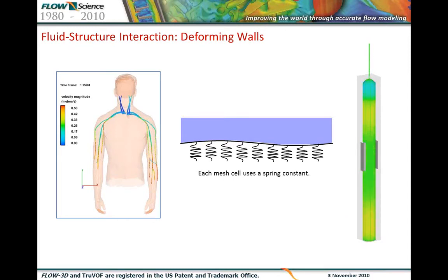As far as the physical details here, the computational cell has a spring constant normal to the surface. This value can be assigned per solid object imported into Flow3D. Also applied in this model is a general moving object model to simulate a prescribed motion of the actuator. Please note that blood is a non-Newtonian fluid, so these moving object models can be coupled with non-Newtonian physics and shear thinning.